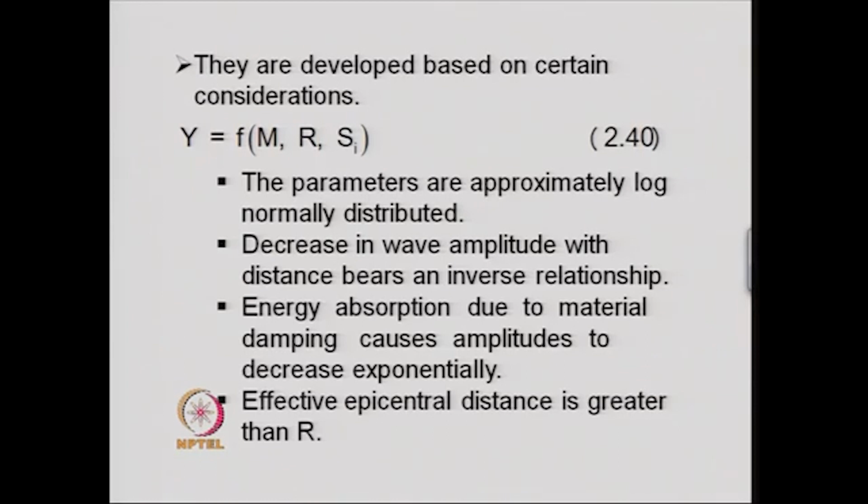Secondly, in obtaining the attenuation law, it was observed that the decrease in wave amplitude with distance bears an inverse relationship. Then the energy absorption due to material damping causes amplitudes to decrease exponentially, and this was also seen from the previous earthquake data.